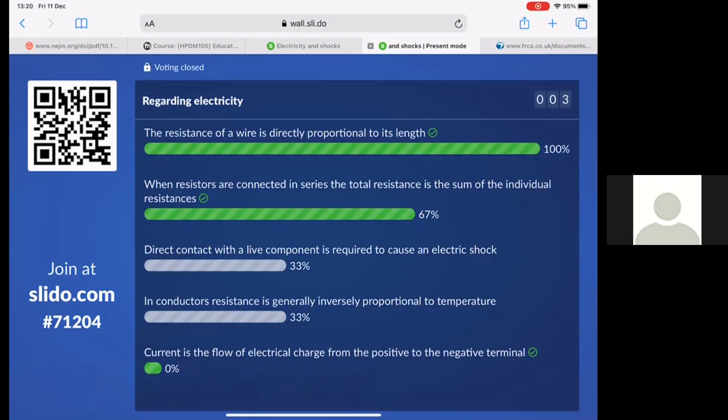Yeah, exactly. This is to do with how currents pass through them. Current is transferred by having free electrons buzzing around. In a conductor, you've always got free electrons, so you always get a flow of current. But as temperature increases, the activity of those electrons increases, they buzz around a lot more, and they essentially provide resistance to flow by getting in the way. Think of it conceptually, whether that's true in physics terms or not, I have no idea. They're moving around, getting in the way, like people nipping in and out of shops on Oxford Street, you can't walk past them.